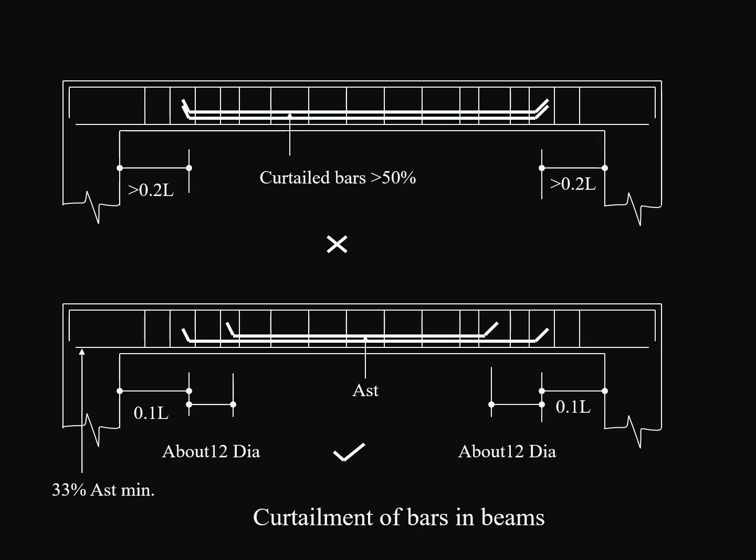Curtailment of bars. Don't curtail the bars at the same point. They must be staggered as shown in the second section shown below.